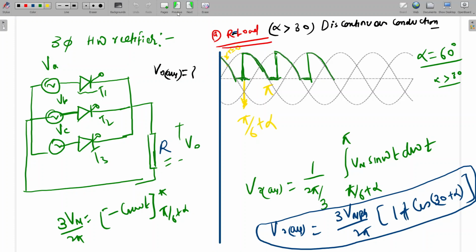I will take three voltages. Okay, three phase voltages first we will plot, and after that we will subtract those voltages in coding form, and then we will see the line voltage. So there we will observe the leading angle in that waveform. Okay. So before starting the full bridge rectifier, I will explain that relation between phase and line voltage, so that we will see with phasor as well as the waveform. Okay. Then it will be more clear.